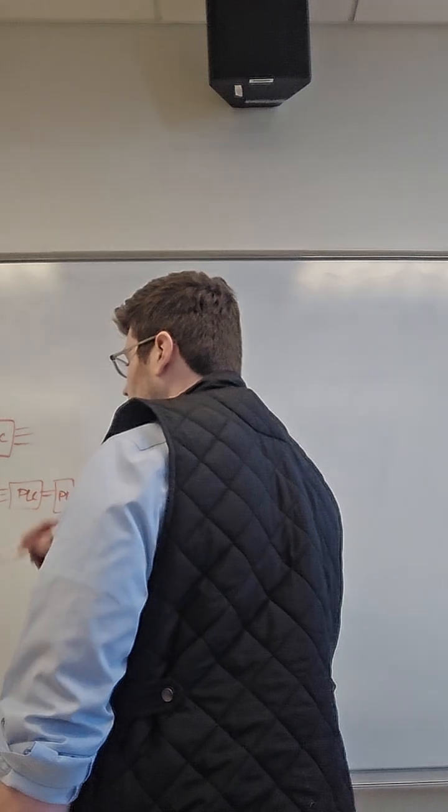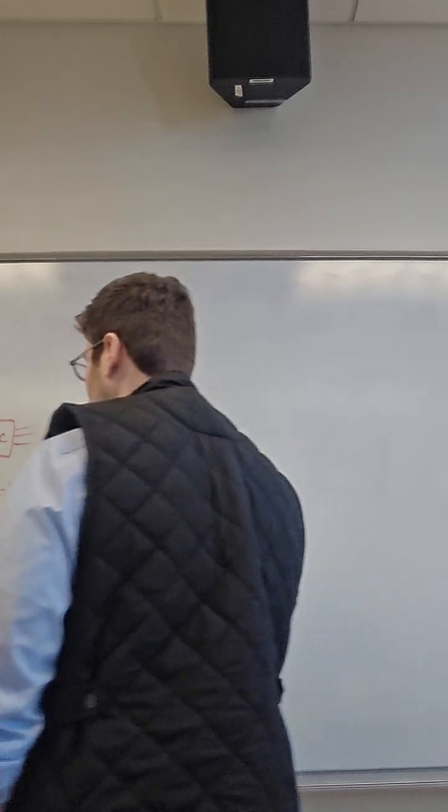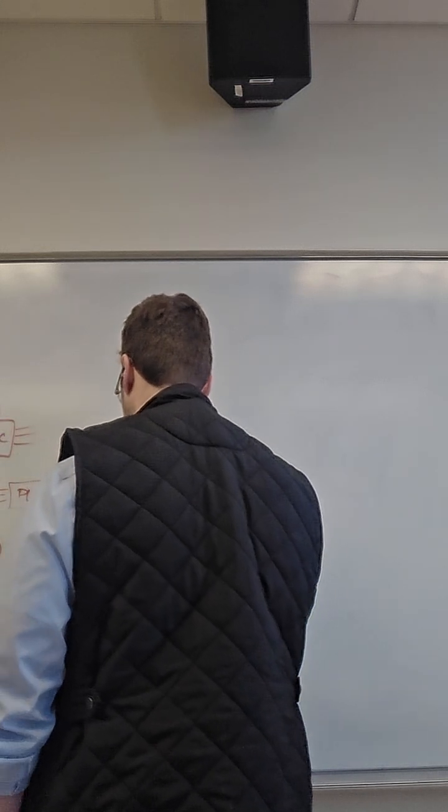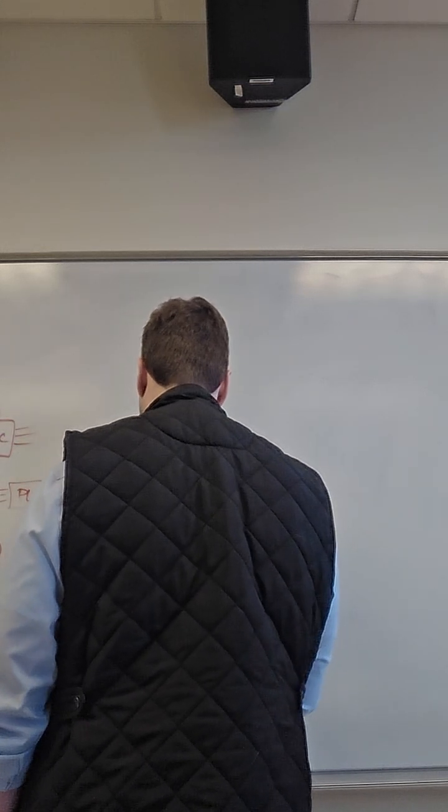The thing you want to know is that there's even addressing in here, because we have to say, hey, PLC number 1, do the thing, or PLC number 4, do the thing, and PLCs 2 and 3 would not do the thing. So for that, we have addressing, where this would be address 0, 0x0, this would be address 1, 0x1, this would be address 2, 0x2, and 3, 0x3.